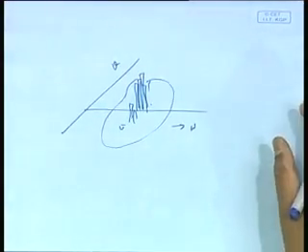People have done it, and as I said, nowadays it is becoming fairly sophisticated to determine directional content from what is known as wave slope. We have ocean satellites collecting a whole lot of ocean data. Besides wave heights, nowadays they are also collecting slopes. Similarly, data buoys keep collecting slopes. Long back it was only wave height, but now you also have slopes coming in, and from there directional content has been worked out many times. So, they look like that. So, this is what is a 3D spectrum.